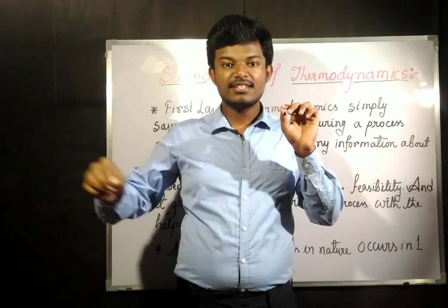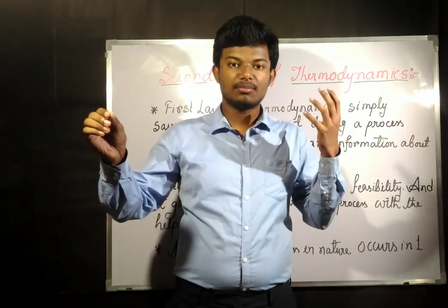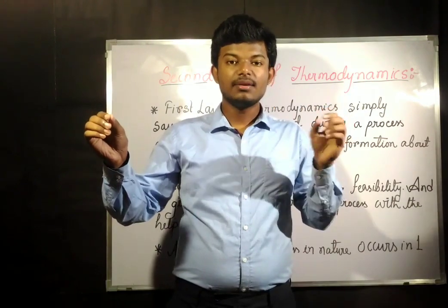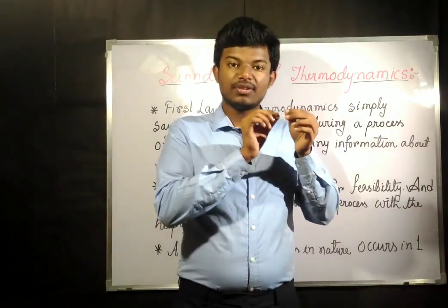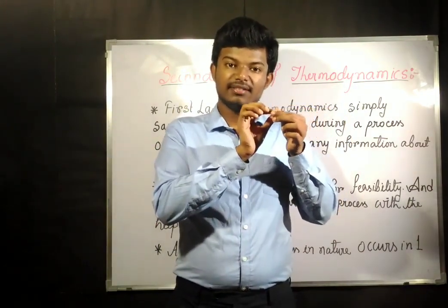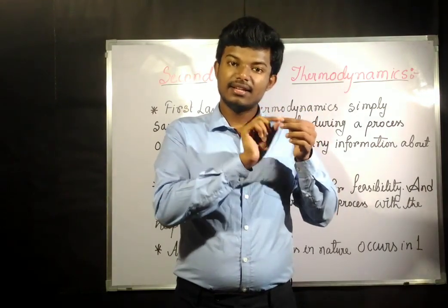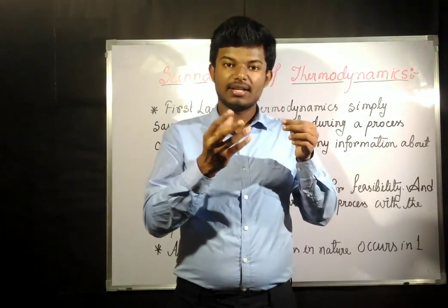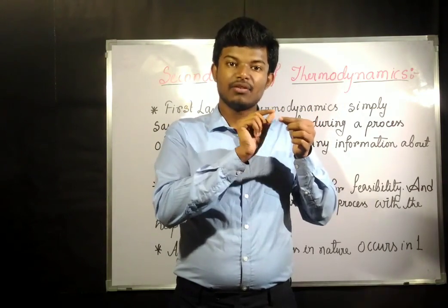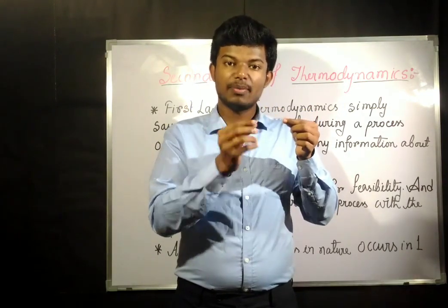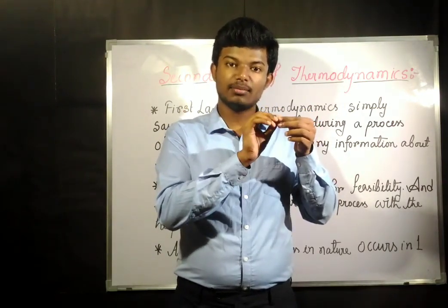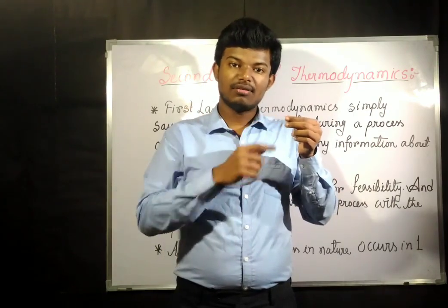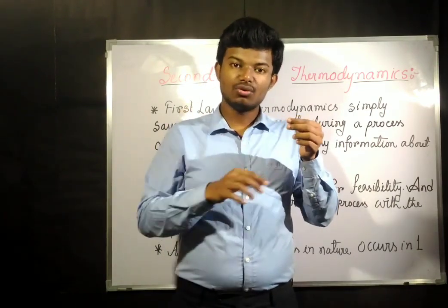That internal energy change is not considered in a cycle. Why? Because in a cycle the initial point and final point are the same, and internal energy is a property. In thermodynamics, any property at a single point is always the same, whether you come back to it after 1 hour or 2 hours.